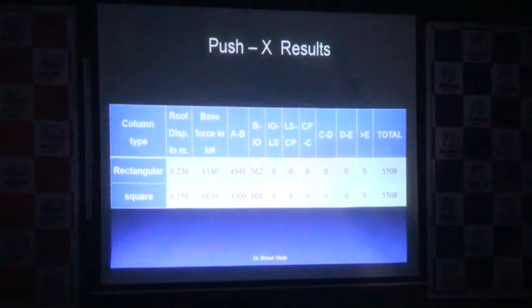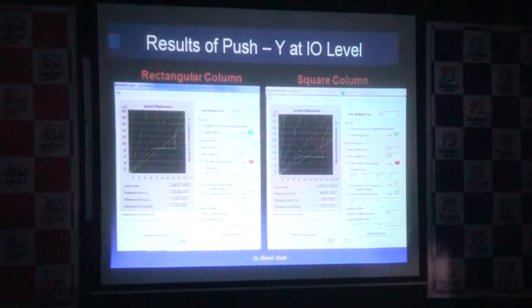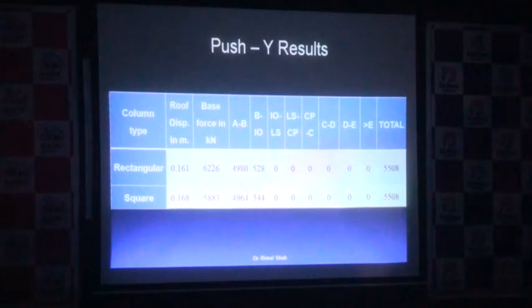So we studied the models under the normal cases. Understand that the first model which we had analyzed was already following provisions, but still the hinges which were developed were beyond the elastic limit, under the same earthquake load. The earthquake loads we are not changing. What we are changing is the properties of the building. And we wanted to find out that if your client says I want my building to be in the immediate occupancy stage only, then do you have a tool to do that? And yes, we have that, and we have done the cost estimation as well.